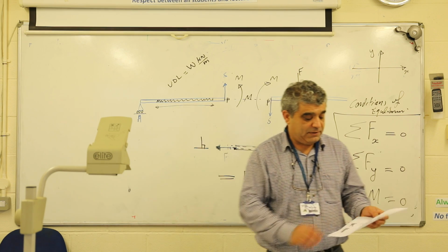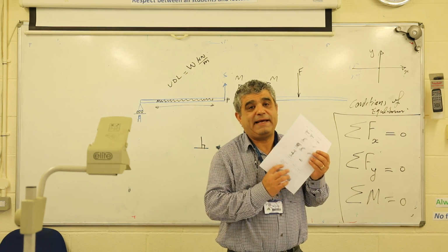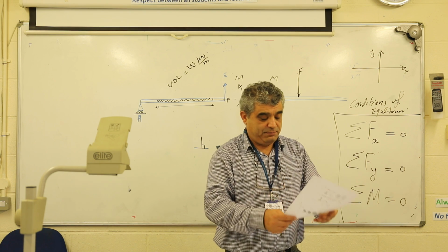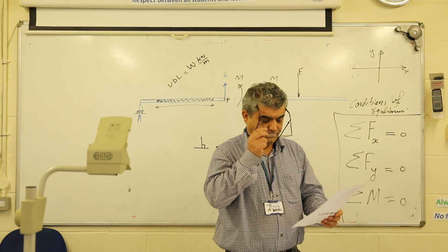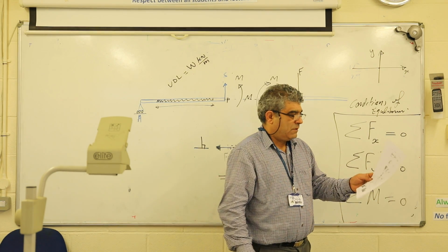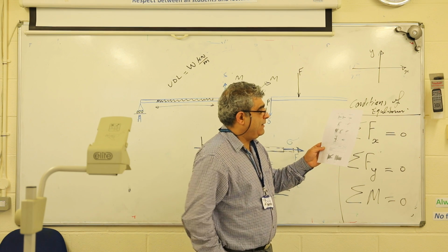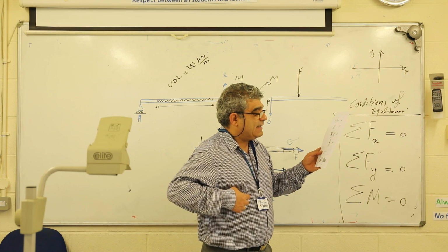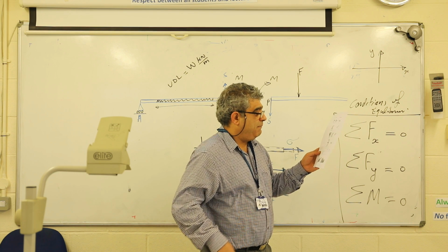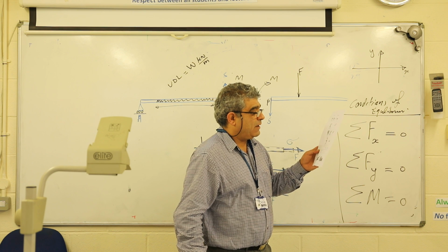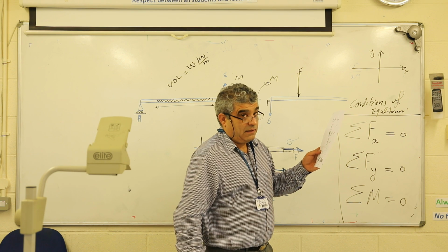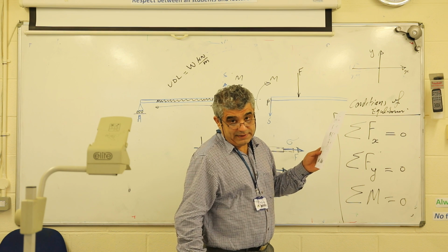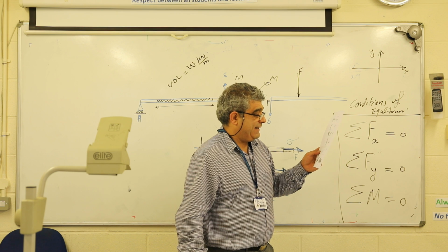And in terms of the reaction force or displacement, the table is there, which you can match. As you can see here, for part A, built-in or fixed support, the reacting force is going to be a reaction in the X direction, a reaction in the Y direction, and also a moment as well. Yes, and I put it as a tick.